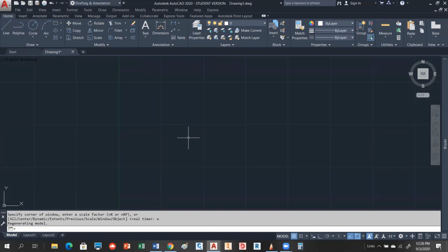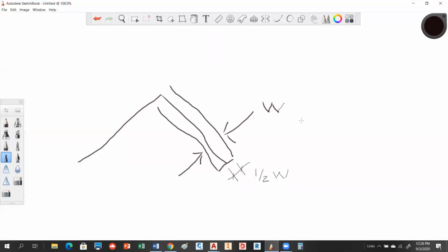So the other option we want to look at is called a close. So a polyline thinks it's either open or closed based on how you draw it. So if I start at a point and I come to another point and I draw it back like this, that looks like a closed polygon, but it may not be depending on how you draw it in AutoCAD. And I'll show you the difference here. And particularly when you have width on, you can tell that. So we're going to leave that width in place.